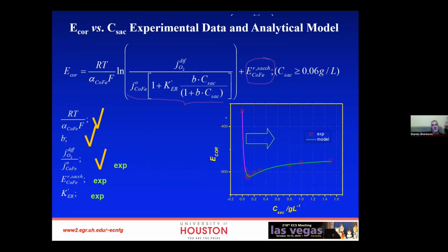So you get a very nice understanding right now that basically, if we keep increasing the concentration of the additives, we will be decreasing the stress in the film. We will not be getting the softest films because we know there is an optimum in concentration that gives the softest film. So more additives doesn't mean softer films. There's an optimum. And we will be getting films that corrode faster.